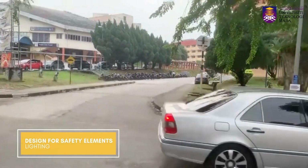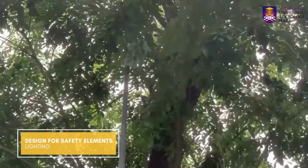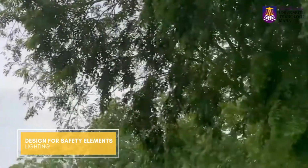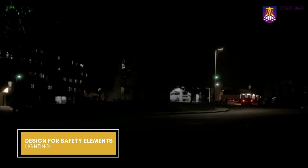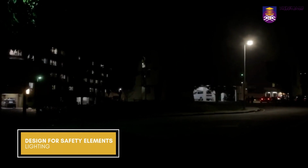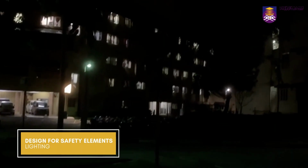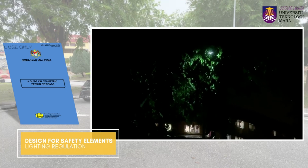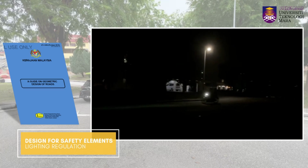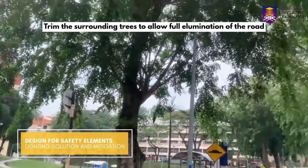Existing street lighting is dim and partially blocked by overgrown tree branches. Tree branches and dense foliage are blocking the light beams, causing shadows on the road surface. At night, visibility is very poor, making it difficult for drivers to see pedestrians or cyclists, especially students walking along the roadside. This creates a serious safety risk and increases the chance of incidents. The lighting poles are not well positioned and there is no effective aid to guide drivers. This condition does not meet the visibility and illumination requirements outlined in Arahan Teknik Jalan 8/86 2005 and the JKR Manual Facility Keselamatan Jalan. Several mitigation steps are proposed.